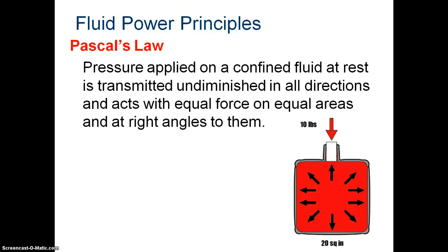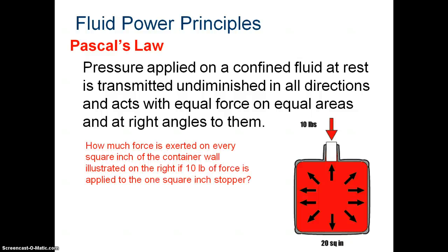Pascal's law says that pressure applied on a confined fluid at rest is transmitted undiminished in all directions and acts with equal force on equal areas and again at right angles. So how much force is exerted on every square inch of this container wall? It's illustrated on the right.